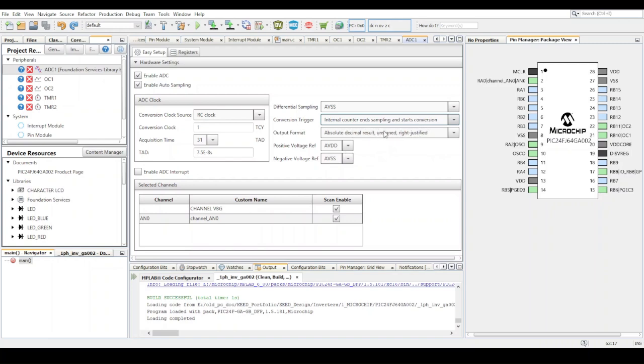This is more of a manual sort of ADC. It doesn't automatically convert. You have to clear the sample bit to end sampling and start the ADC conversion. And obviously you could use INT0 as a trigger as well, or timer 3 as a trigger.